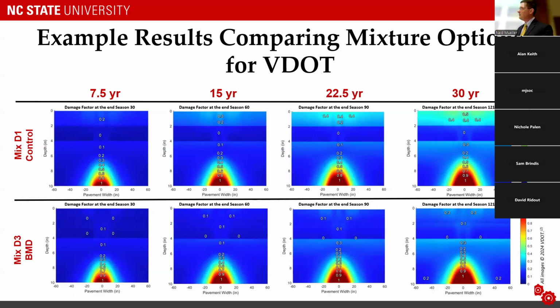And that mixture on the bottom has been engineered to a higher degree than the one on the top. And specifically, what's been done is that we've used what's called a recycling agent or rejuvenating admixture in the mixture. We've also lowered the binder content to make it a little softer, which helps to facilitate fatigue damage resistance. The one on the top is a control mixture. That is, again, a normal mixture by normal design features. It doesn't have that engineering embedded into the mix design. And what we do with this tool is see what's the actual benefit of that.